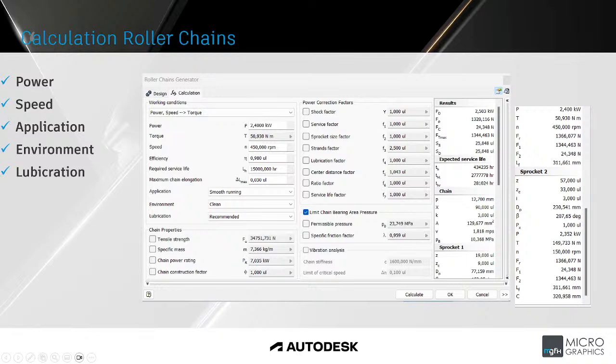In this instance, I selected the power speed to torque, and the power I made was 2.5 kilowatts. The speed I made 450 RPM. The efficiency I left as is. The required service life I chose 15,000 hours. The application I made smooth, environment I made a clean environment, and lubrication I made recommended.